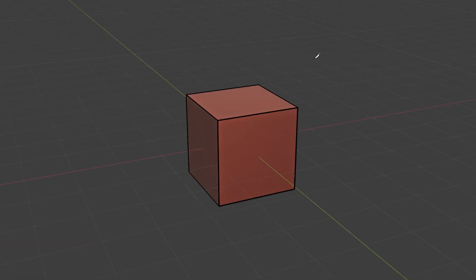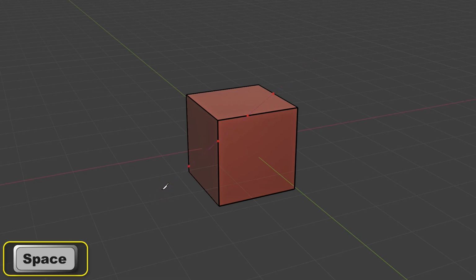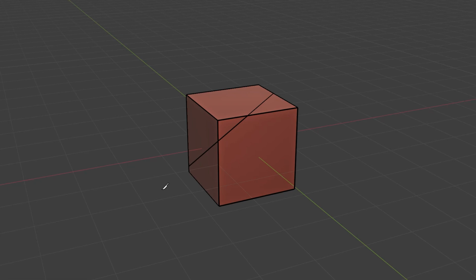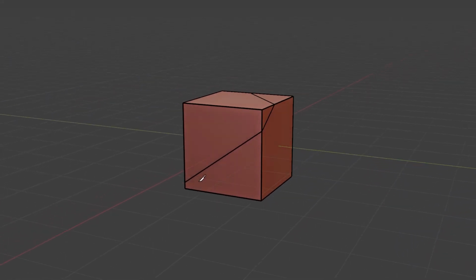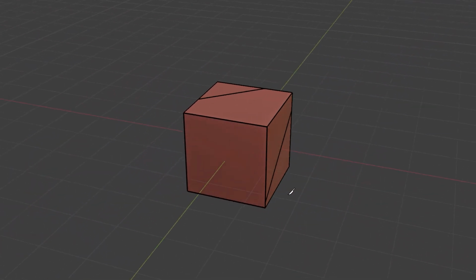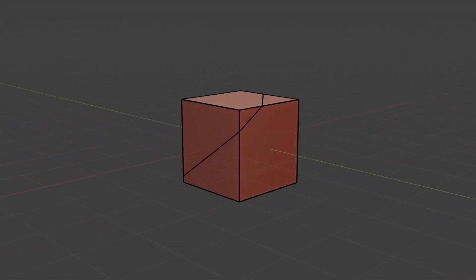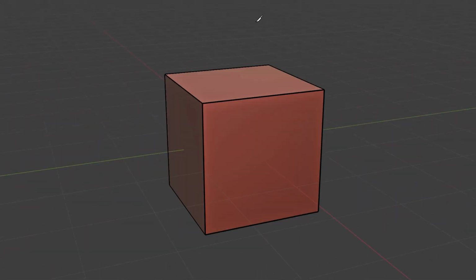If we started the knife cut operation by clicking and releasing the left mouse button, the complete cut will appear as a straight line, and all the intersection points will relocate as we move the mouse pointer. To complete the cut, we need to click the left mouse button and then press Enter or the space bar. This straight line is an illusion caused by our current viewpoint, and we can see the actual new edges more clearly when we move to a new viewpoint. We can combine both cutting methods by simply clicking each time we want to fix an intersection point.